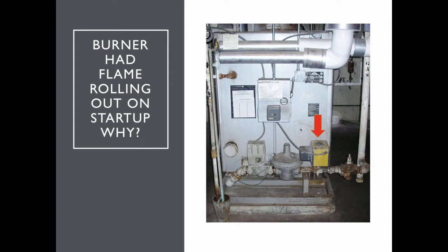It's been 30 years, and I told the director of maintenance what we want to do is look at switching this over from putting the gas pressure regulator upstream of any electric gas valve. And he said, nah, don't worry about it. It's been like that for a long time. So on something like this, you want to log what's going on so you're not blamed for it.